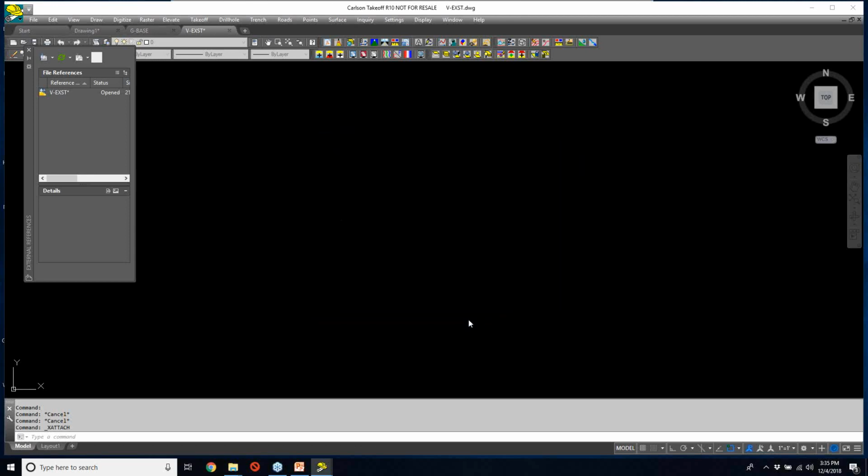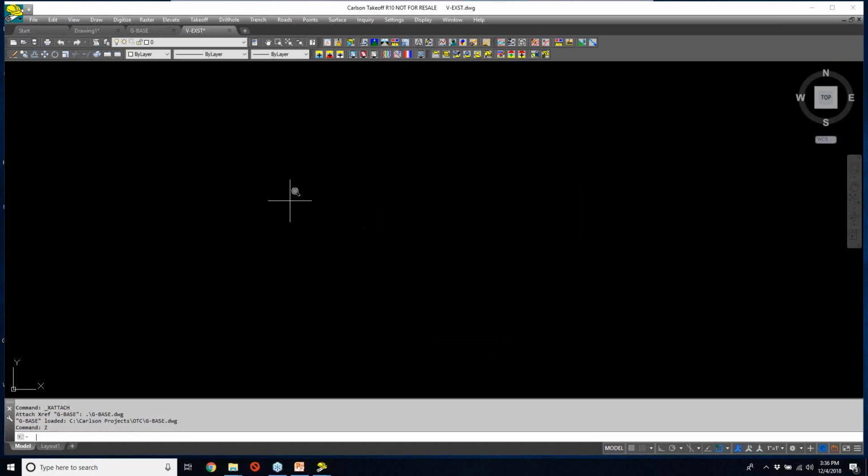And with that, I will have an external reference attached into my survey drawing. What that will let me do then is get to the geographical position of my first plan set without really physically having too much data in my overall survey drawing.